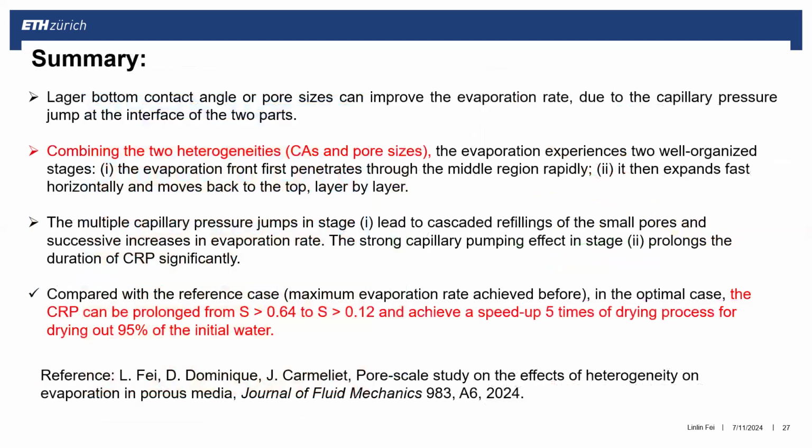So let's go to the summary. I found based on lattice Boltzmann simulation, if we want to do evaporation in porous medium, if we have larger pore size or larger contact angle in the bottom, actually we can increase the evaporation rate. This is due to a pressure jump at the interface of the 2 parts. And we can combine these 2 heterogeneities.